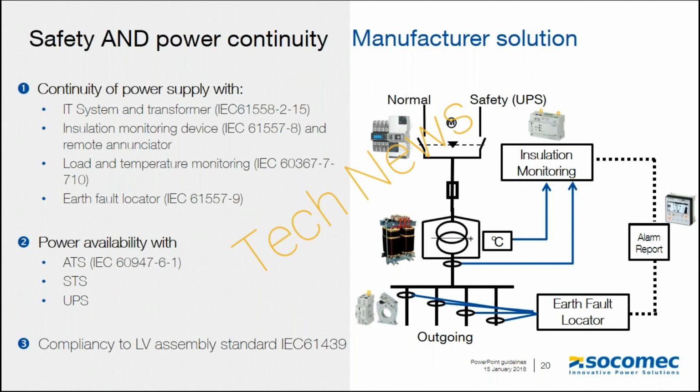And for LV assemblies, there are IEC compliances to ensure proper design and operation. Therefore, in a mission-critical application, such as the medical location, IEC 61439 for the IPS panel should be adhered to. So what is behind the IEC 61439? It means that the LV assembly has been designed, qualified, and tested by respecting the 13 points inside the standard. The main criteria, for example, are short circuit withstand, IP protection, and withstanding temperature rise. And the temperature rise tests for IPS is particularly important due to the integration of the isolating transformer inside the cabinet.